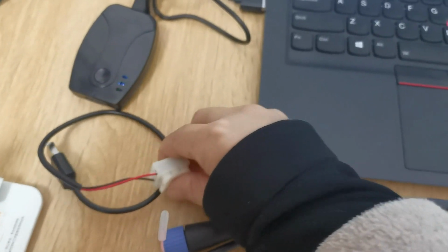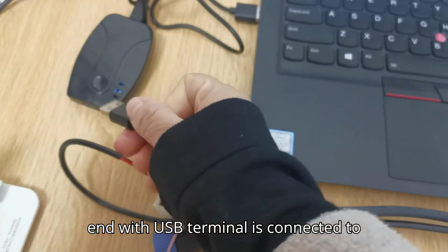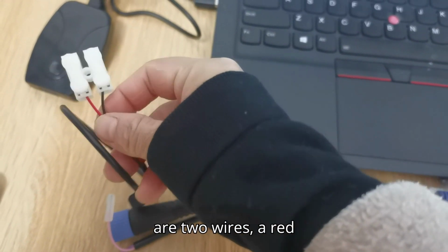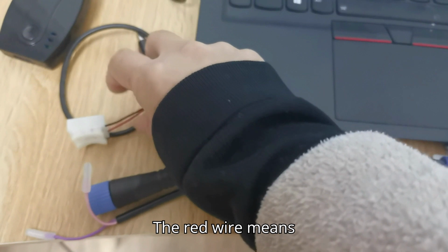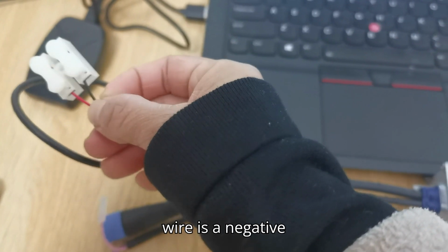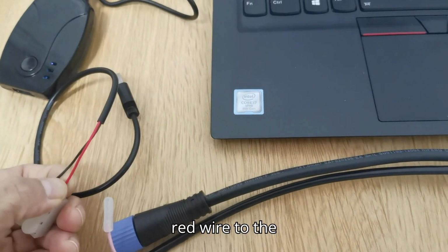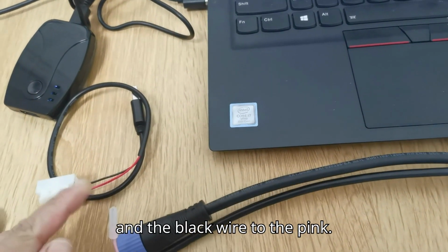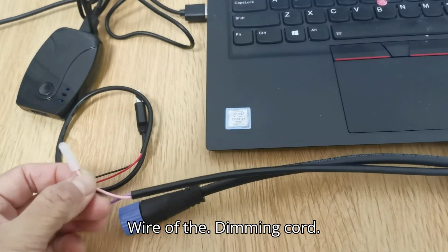And we can see the connection cable. One end with a USB terminal is connected to the programmer. At the other end, there are two wires, a red wire and a black wire. The red wire is the live end, and the black wire is the negative wire. So we have to connect the red wire to the purple wire of the driver's dimming cord, and the black wire to the pink wire of the dimming cord. Let's do it.